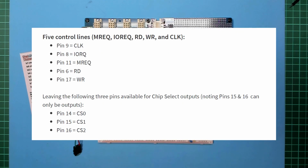Then we have 5 control lines: memory request, I/O request, read, write, and the clock signal. So Pin 9 is the clock, Pin 8 is I/O request, Pin 11 is memory request, Pin 6 is read, and Pin 17 is write.